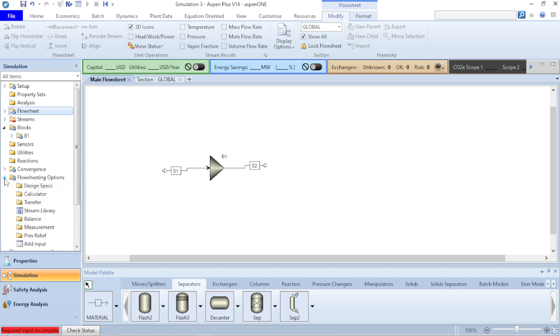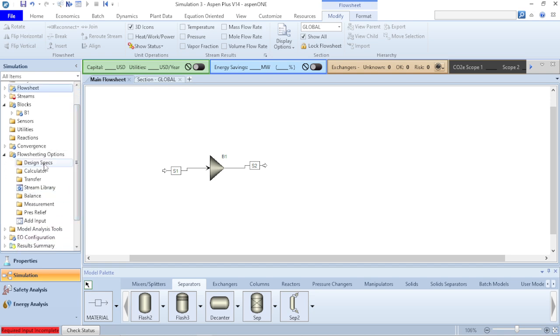All right, then your flow sheet options, design spec, calculators. If you have any of those things to add, it's just like some operational blocks, some logical blocks you can be adding to help with your system calculation and all that. All right, then you have your model analysis. This is where you'll be carrying out sensitivity analysis, optimization, putting in your constraints, your data fit as well.